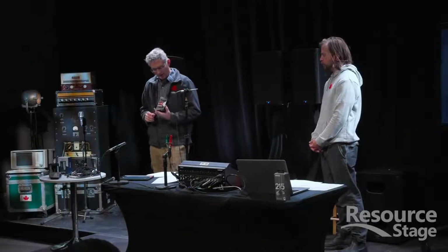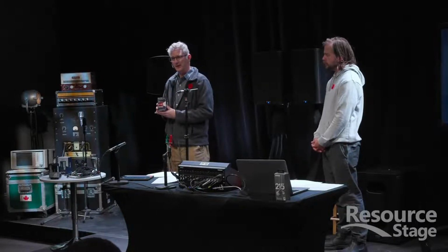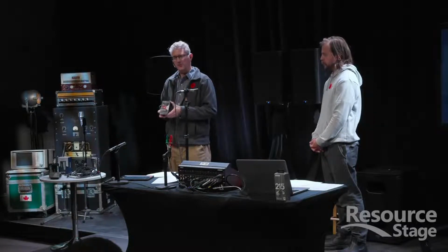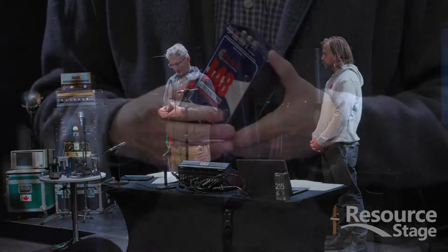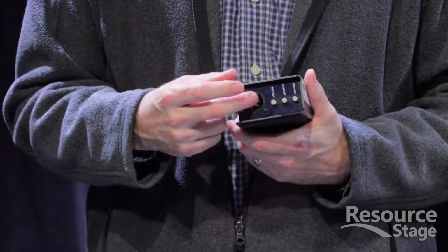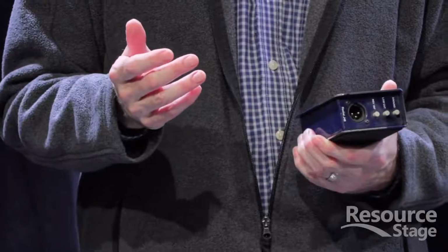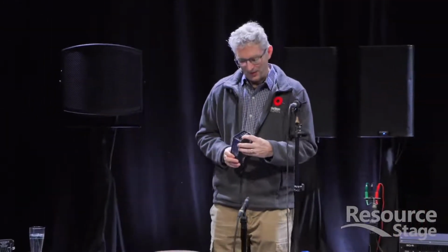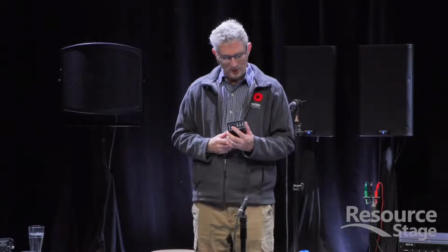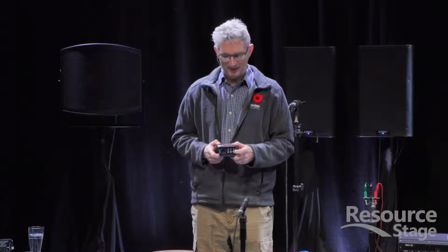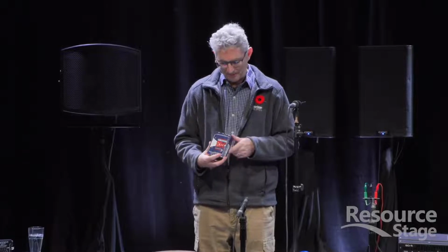And then we've got this J48. This is an active direct box, so it requires some sort of power. Normally, these days it'll come through the phantom power from the mixing console. Does everyone know what phantom power is? Yes. Okay. So that's handy. If you do press the ground lift switch, it is not going to cut off the phantom power. This thing will still keep working. On the older models, that would happen. So that was an issue that they've overcome.